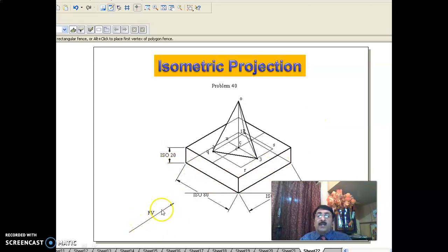Okay, I have given the front two direction as this. If you take the front two direction as this, a square, this is anyway a square, no? A side of the square is parallel to VP. Okay, this can be seen in the front view. And if you take the top view, that is the top solid, again 1 to 2 is what? 1 to 2 is an edge of the triangular pyramid, again perpendicular to VP and to the left of the observer.